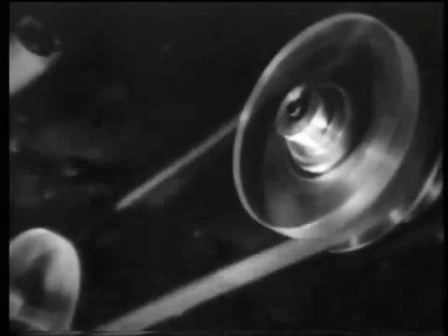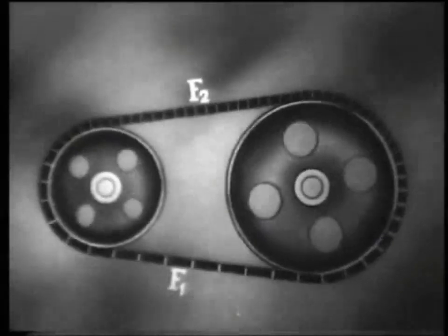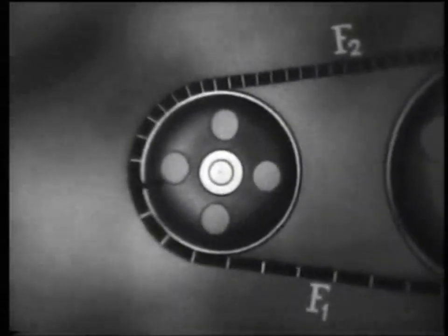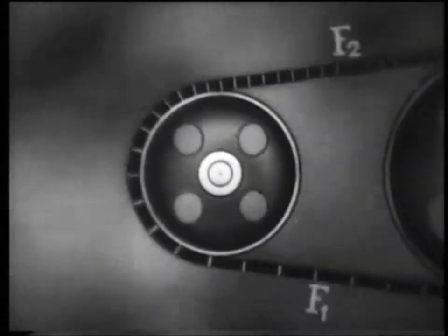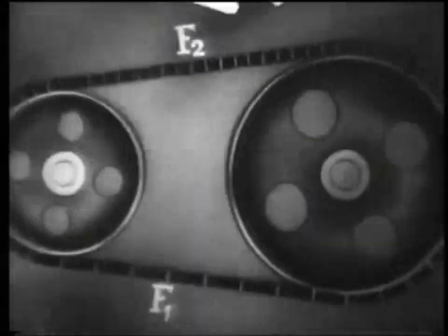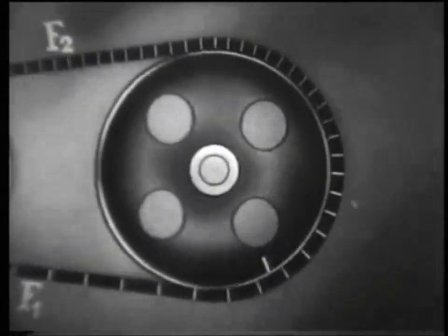When the belt runs onto the drive pulley, its tension force decreases, and each element of the belt shortens and lags behind the pulley. During the run onto the driven pulley, the belt tension increases, and the belt elements lengthen and outstrip the pulley.